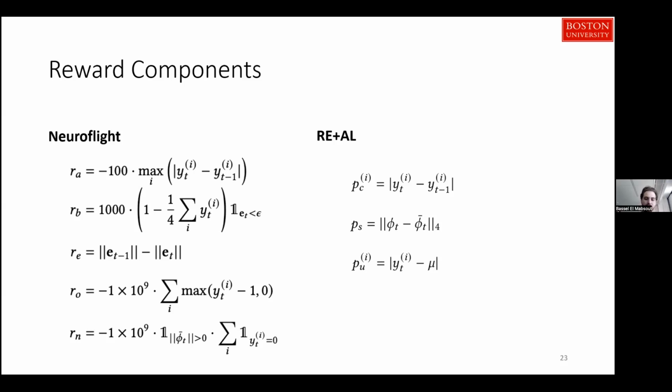This input is easy, because there's no complicated thing you need to apply to achieve your intent with respect to following those set points. You can represent it as the distance between how fast this thing is rotating around the axis and how fast we want it to. It's rotating at this speed, we want it to rotate at that speed. That's our error. This is the thing we want to minimize. This is the trajectory we want to follow. So really, it's not a difficult problem in that sense, at least for quadrotor control.